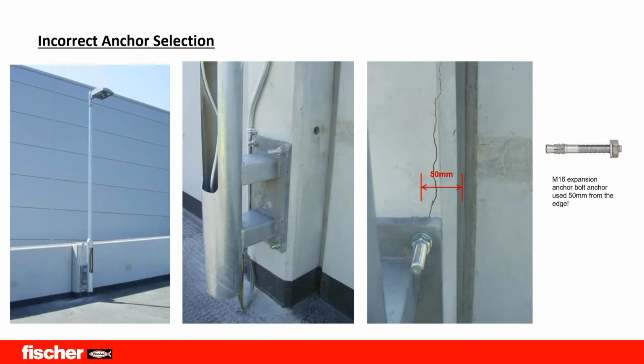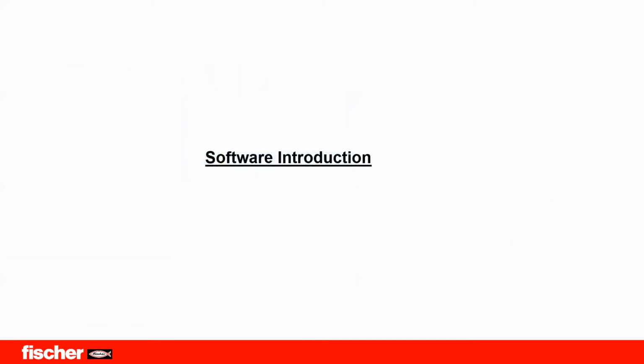As we all know, a chemical anchor works by bonding, so it doesn't put too much stress on the wall of the drill hole. Therefore it was perfectly fine using a chemical anchor. Our advice would always be to go with a chemical anchor if you have a close edge from the concrete.